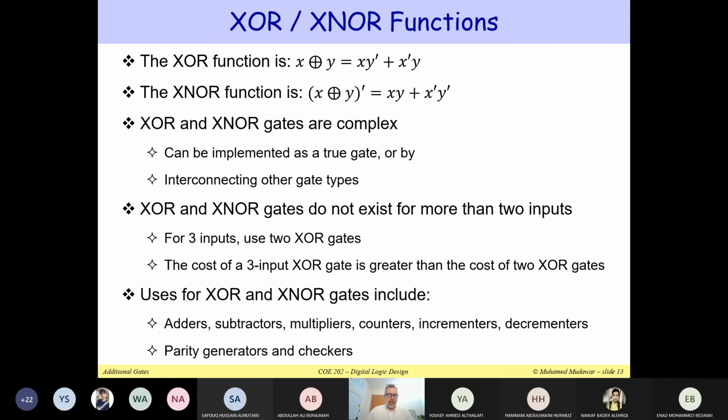And if I would like to write the exclusive OR as a sum of products, I can say X XOR Y. I can write it as XY prime or X prime Y. Now notice that XY prime, what is this minterm? It's 1, 0, right? So this must be minterm 2. Exactly, minterm 2. And how about X prime Y? That will be minterm 1. Exactly. So it's minterm 1 or minterm 2.